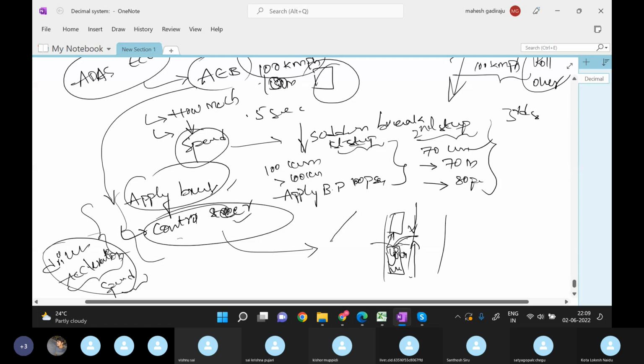So this is what LKS and LDW are. Lane keeping assistance, what will it do? If you are going this way and trying to turn the steering, then definitely you should turn on the indicators. Without turning on the indicators, if you are trying to change the lane, first it will give a warning on the HMI, which is the dashboard. It will think that you are sleeping or doing something and unwantedly trying to change the lane. So that is lane keep assistance.